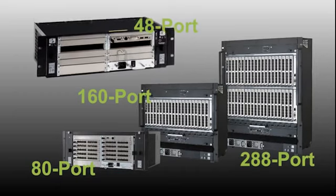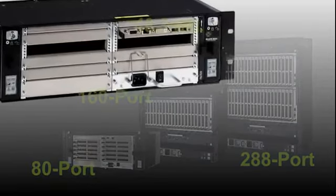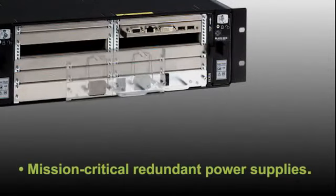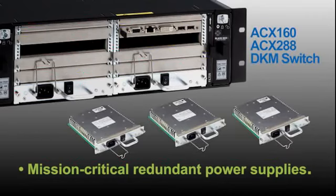The 48 and the 80 port chassis will allow you to support redundant power supplies, up to 2 maximum. If you go with the 160 or the 288 port, you can use up to 3 redundant power supplies. This will allow you to have redundant power input, or if you prefer separate mains coming in, you can use that instead in case one power input goes bad.